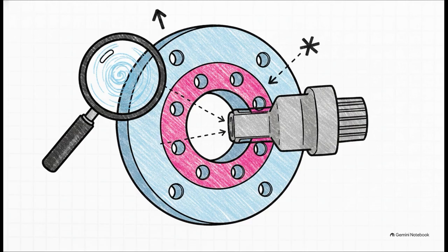So applying that golden rule back to our flange, the answer is pretty clear, right? Because our inner ring mates with that precision-located shaft coupling, it acts as the functional anchor, so it should absolutely become your primary pattern datum. Now, the standard does throw in a few practical caveats. The datum feature obviously has to be accessible, and it needs to be of sufficient size to actually be usable. But since our inner ring handles that high-precision mating component, it checks the functional box perfectly.